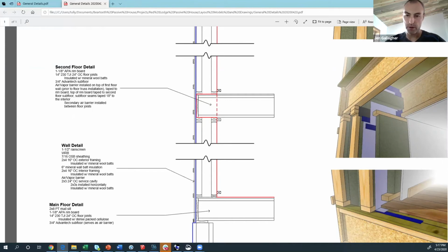How do you secure the perpendicular 2x4s to the bottom of the wood trusses? Derek, I use 6-inch, they were not GRK screws. The local hardware store carries big fasteners by a company called Big Timber, and they had 6-inch structural screws that I used to attach those.